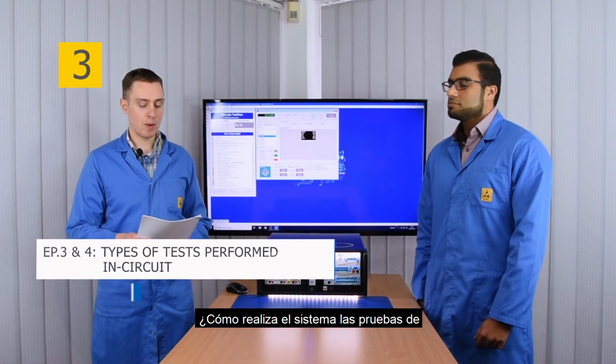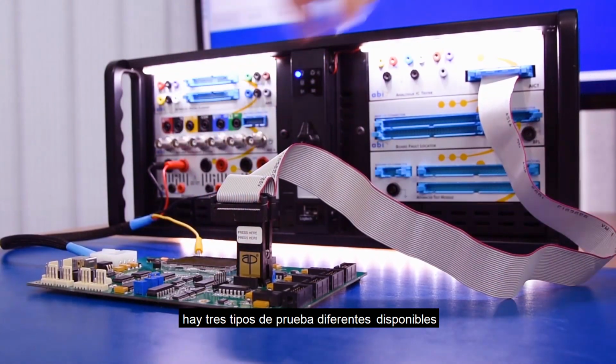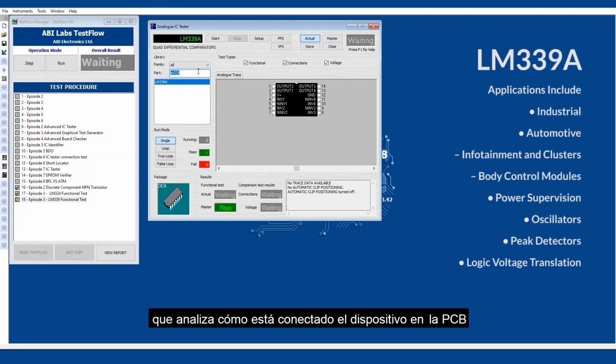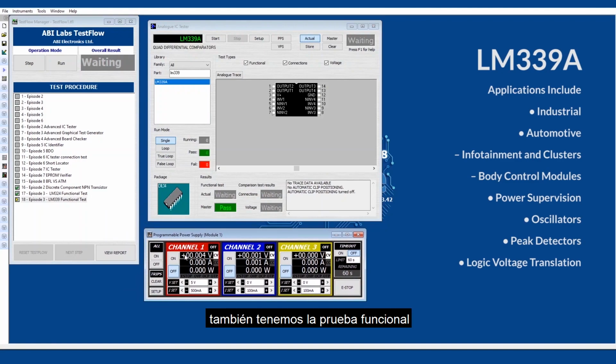How does the system go about testing the different analog components in the library? Okay, so there's 3 different test types available. We have a connection test, which looks at how the device is wired on the PCB as it is. We have a voltage test, which looks at the voltage on each pin at that particular moment in time. We also have the functional test, which basically makes sure that our device is operating as it should be.